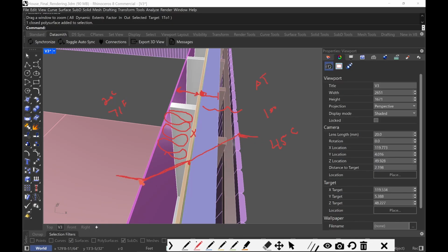This is like the temperature difference. And we'll say this is the dew point right here. This doesn't quite make sense, but you get what I mean. So if you don't have some cavity insulation, they're saying that this is going to be a huge, drastic change of temperature between here and here. So it's going to condense a lot.